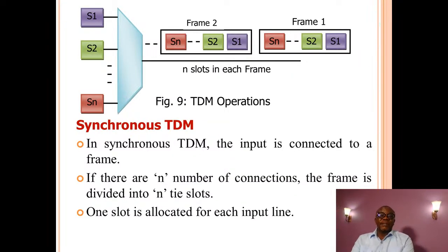So now, look at basically how TDM works. You see signal 1, signal 2, up to signal n. They have the same frequency. They are not the same thing as F1, F2, Fn. So what the commutator does, which is in the mux, is to sample very fast S1, S2, S3 until Sn. Of course, he knows the starting and the ending.